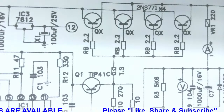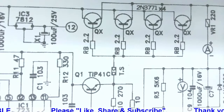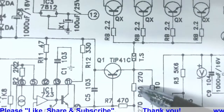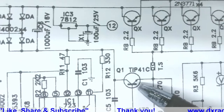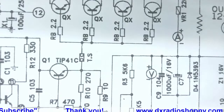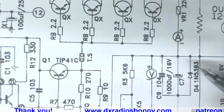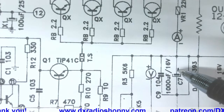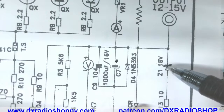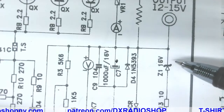Okay. So got your resistors. They're using boxes, but these are all resistors. There's another regulator, but that's a transistor symbol. Here's your capacitor. So they use this symbol here, where it's dark on one side and kind of a box on the other side. That's your polarity, which means this side here would be your plus. Okay. Remember we talked about the Zener diode with that little squiggly line? 16 volt regulated diode. That's a Zener diode here.